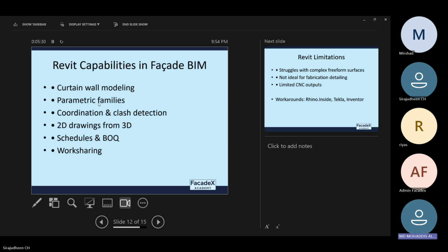We will have to create it here in Revit, right? We cannot import the CAD file. No, we cannot directly import it from the CAD file, but we can use the CAD file as a reference to create that in Revit. We cannot simply load the profile from AutoCAD and directly convert it into a mullion. That is not possible. That is not how Revit works. But we can just use it as a reference.